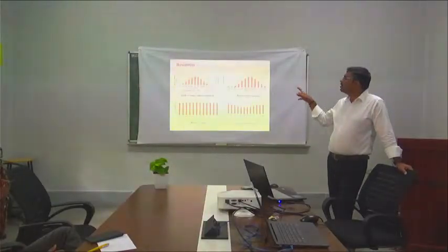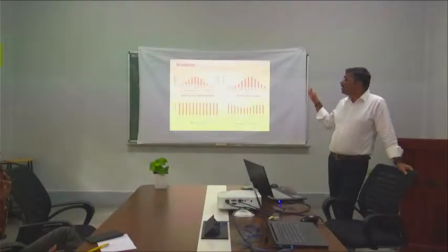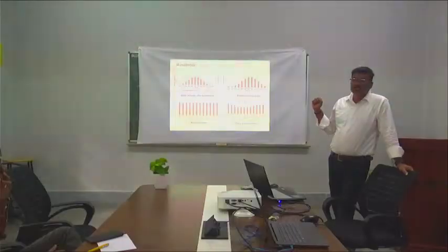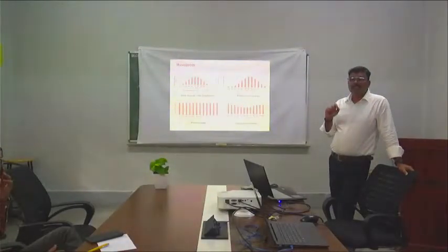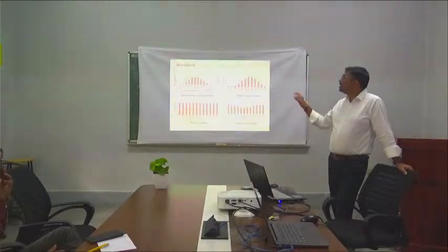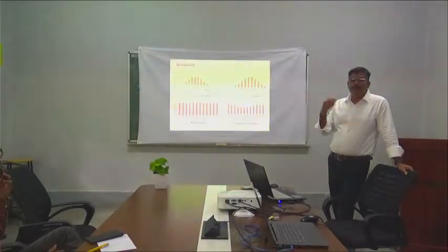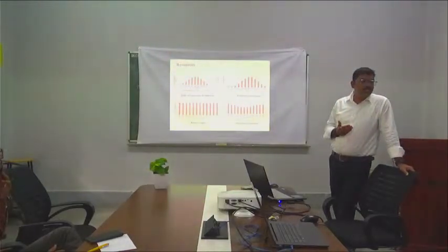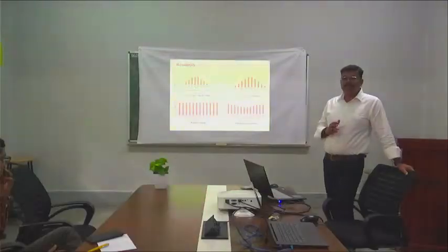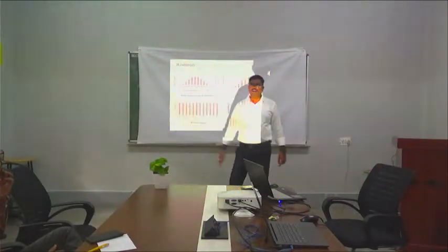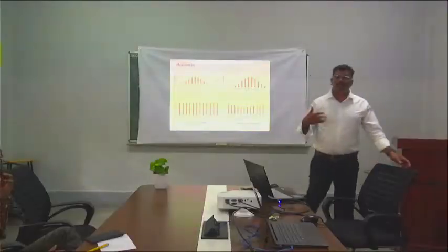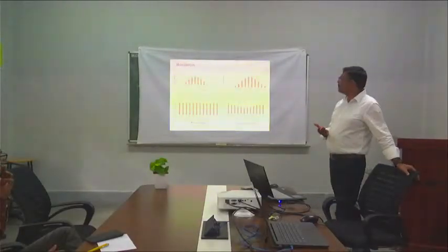That means the resources selected are solar irradiation and temperature for that particular location, and biomass input I consider as a constant. I assume that some 8 tons of biomass is coming from that particular university. If you want to change the biomass, you can take a different value here also, and your analysis will start again.